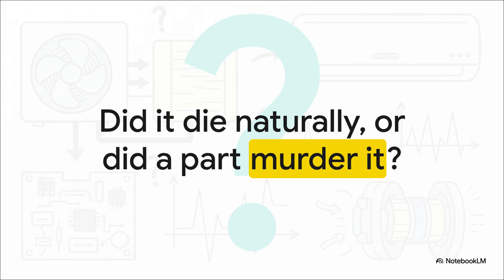Well, as we wrap up this Level Up HVAC training explainer, I want to leave you with a really crucial mindset shift. As a master technician, when you open up a condenser out in the field and you find a burned-out inverter board, you always have to ask yourself, did this board die of natural causes, like a random power surge, or did a failing component murder it? Think about it. A shorted compressor winding or a grounded motor will instantly kill a brand new, expensive board the very second you power it up.